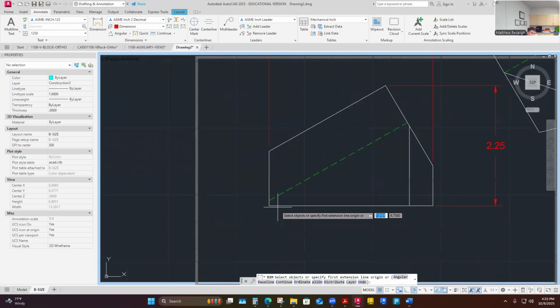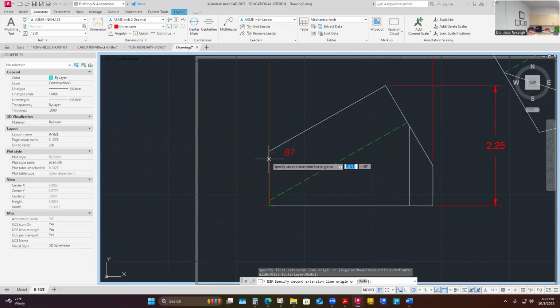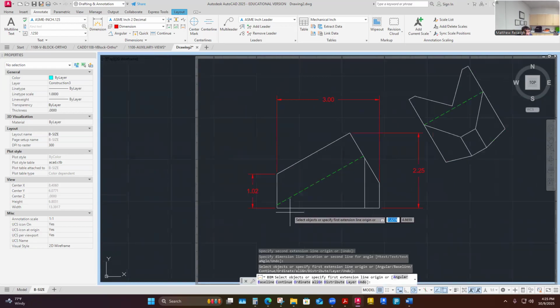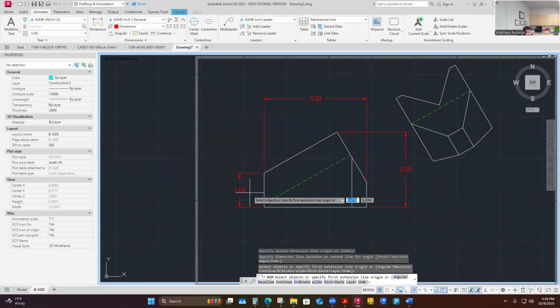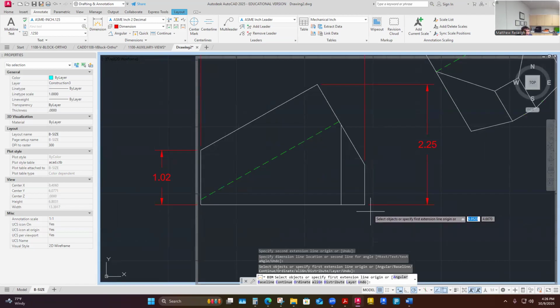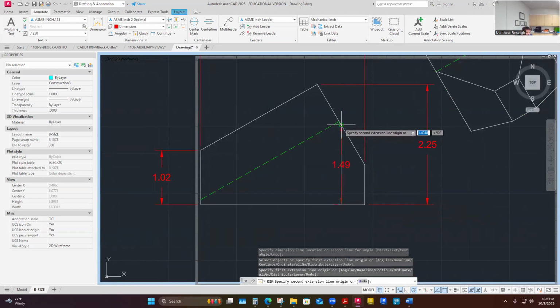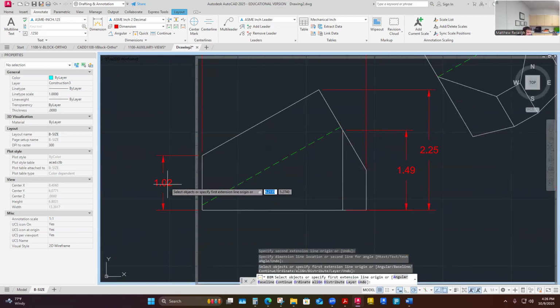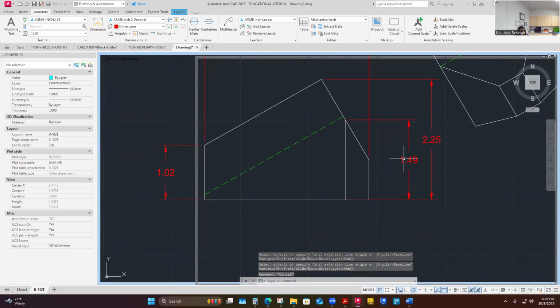It's definitely got this side. This might be the best side for it. I'm pulling off the bottom, so that's good. It's pulling off the bottom control. I like that. Whether I snapped it over here or over there, I'm picking there because I'd have to have a really long extension line across my object clear to the other side. So for no other reason than clarity's sake, I'm moving that to the left. This one here, I'm going to put to the right, for clarity's sake, and that's where I would prefer things to be, in between the views. So I've got a rule breaker over here, but it's a good place for it. These are following better rules. So I'll adjust my extension lines as I do this so I don't forget later.